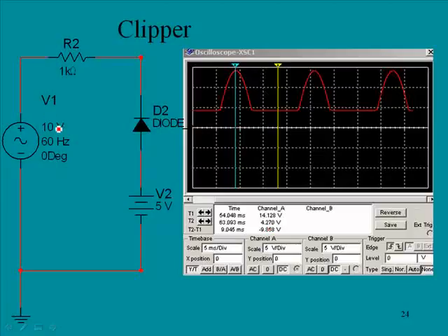We come in with a 10 volt RMS signal, and we usually evaluate this in terms of peaks, so we would divide that by 0.707, and this will result in an AC waveform with a peak value of 14.1 volts. And if you look on our oscilloscope here, you'll see number 1 here. This is in fact 14.1 volts.